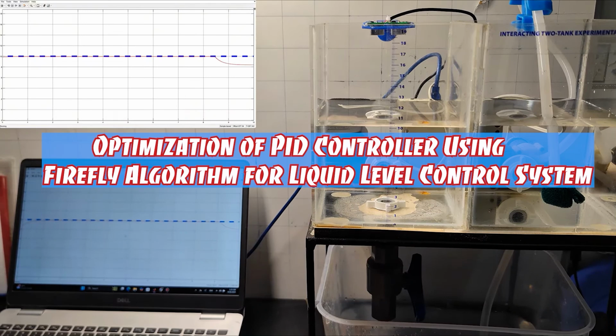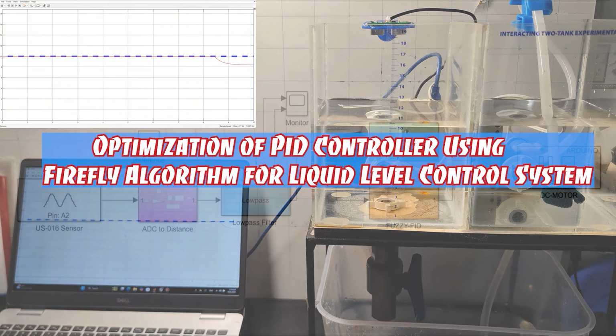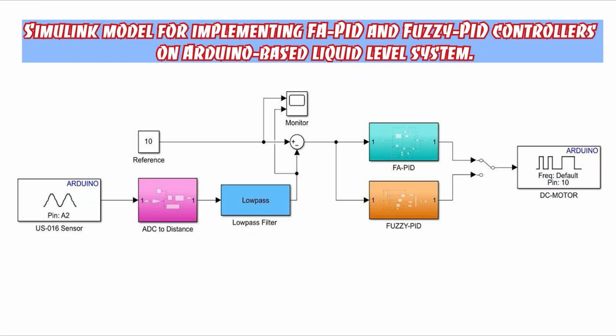In this video, I demonstrate the application of a PID controller optimized by the Firefly algorithm for the liquid level control of an interacting two-tank system. The liquid level is measured by the US-16 ultrasonic sensor and sent to the Arduino via pin A2. The signal is then converted to distance in the ADC to distance block and passed through a low-pass filter to